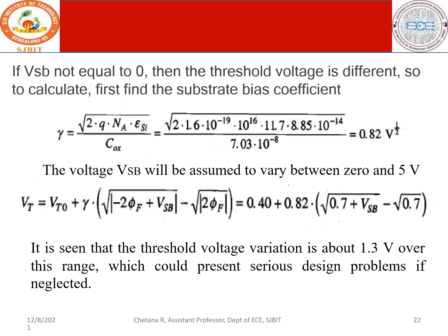and definitely that is going to cause serious problems, because the appropriate threshold voltage is what helps us to go ahead. So I just wanted to show the difference, to understand what the long channel threshold effect is, what the formula is, and what the value is by considering a proper problem. That is case number one. In the second case, we have also assumed the substrate bias. By having an appropriate substrate bias, the threshold voltage is going to vary by 1.5 times. That difference is what I wanted to show, and that is what has been shown now.